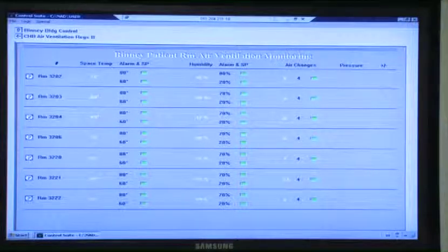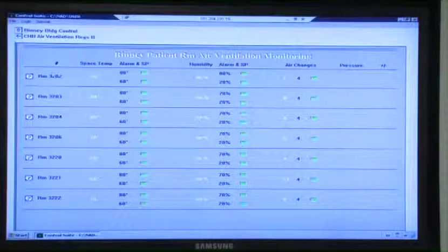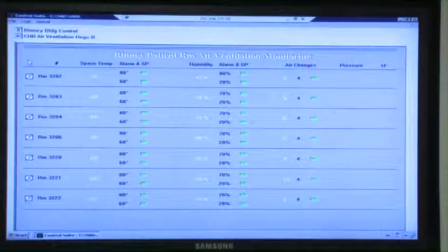In other words, you come to here and you need to have a report on room 3202. You'd go into the historian reports, go to the canned report, air regulation, room air regulation stuff. You pull down the drop-down menu of 3202, and then it's going to automatically print you the report with your date ranges and all that stuff. Make sense? It doesn't make sense to a lot of people because you don't know that part of it, but Jimmy does. You know what's going on with that now. We'll share that as time goes on, how to get that information.